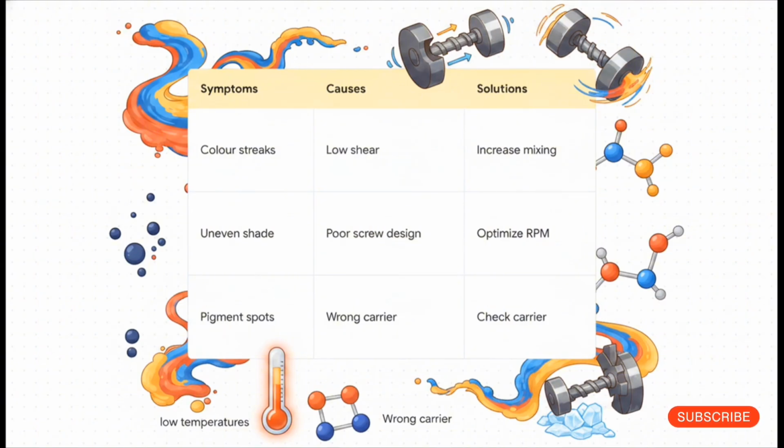Your solutions? You've got to step up that mixing efficiency. Optimize your screw RPM to generate the right shear, and absolutely always double-check your carrier resin compatibility.